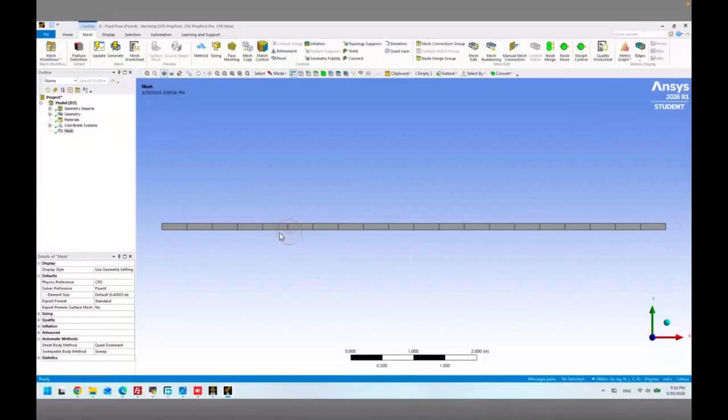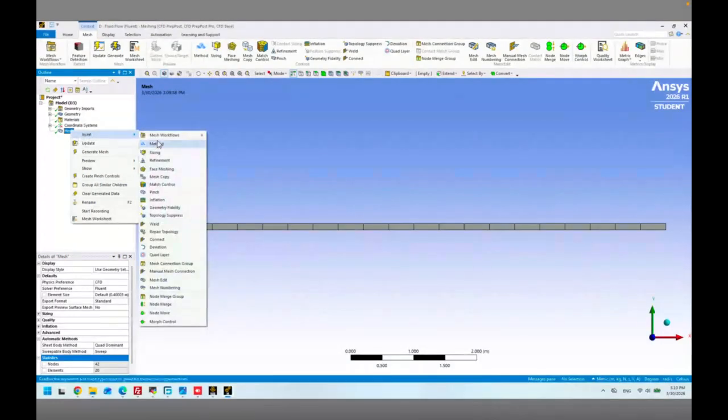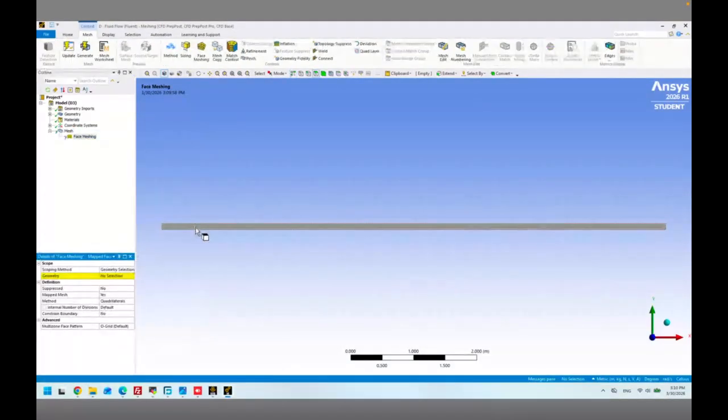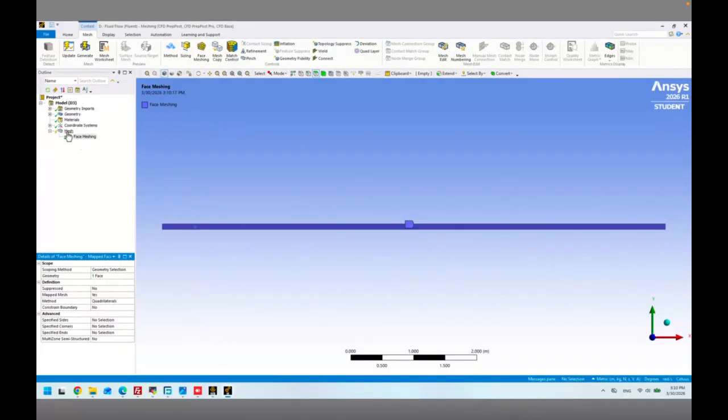First of all, just generate a random mesh to see what happens. As you see, this mesh is very coarse. Coarse is not good. We only have about 20 elements, and 20 elements will not be able to fully solve the problem. That's why we have to modify it and make it finer. Coarse is bad and finer is higher quality.